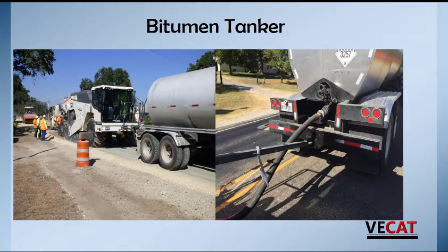In this slide, we have the truck connections from the machine to the hot oil tanker for the use of bitumen foam. If it's an emulsion job, the setup will be nearly identical. The biggest difference with foam is we're dealing with a dangerous hot material. Asphalt needs to be 320 degrees Fahrenheit or higher when it's in use. Typically that means when it gets to the job, it has to be 330 or better. So we need to take a lot of precautions about hooking up to connections of the machine and the tanker, as well as the hoses when we're doing this process.